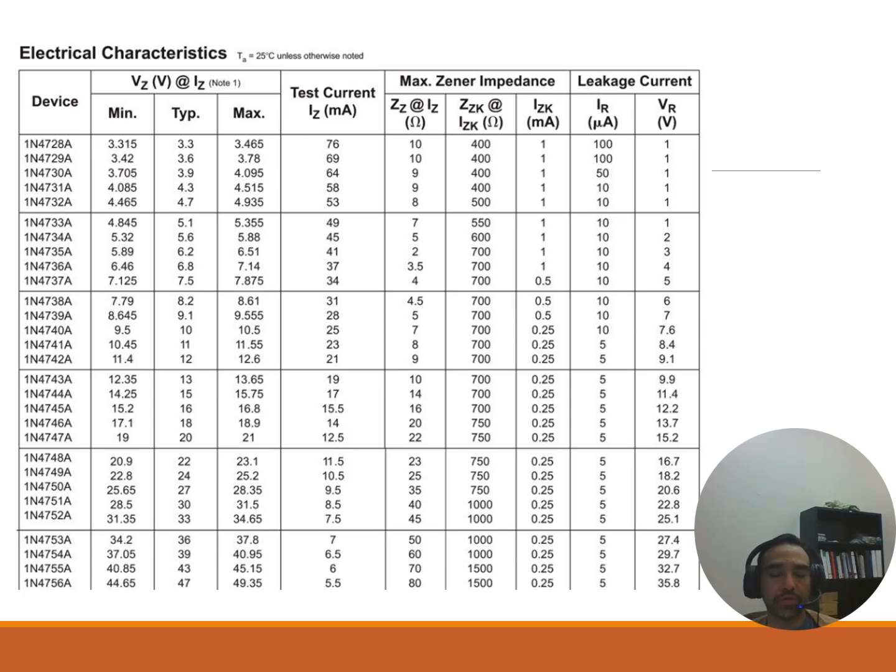There's also something related to leakage current, which is a safety factor for devices. It's not just that leakage current goes through the circuit when it's not supposed to and interferes slightly with the operation of the circuit, but it also increases the leakage current generated through capacitive effects from the circuit board to the casings of devices, and it also adds to that potential hazard, right? Because leakage current is a hazard for people. And that's pretty much it.